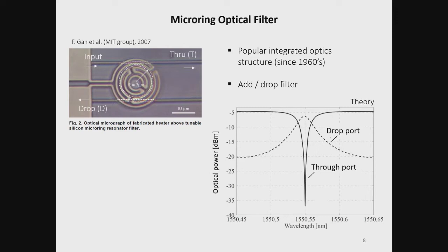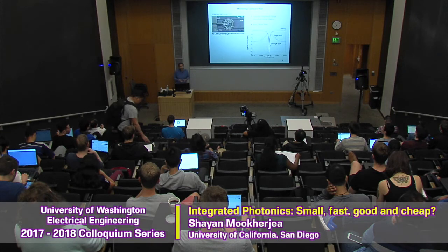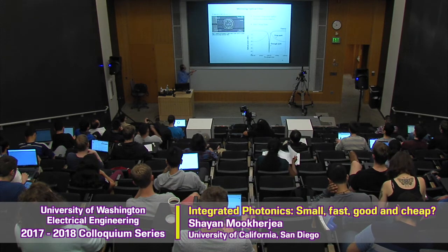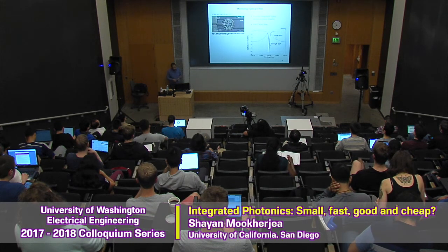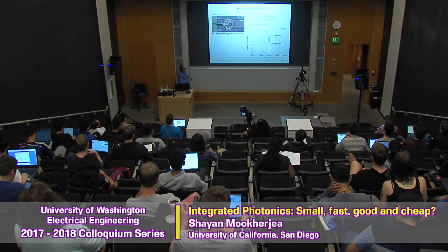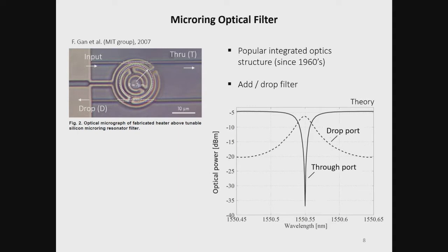In this particular example, you can't see the optical waveguide. That's sort of intentional. I'm trying to show integrated optical examples. There's a micro heater on top of it. This serpentine metallic pathway is just a small heater that tunes the resonance frequency of the ring. This is popular. The cartoon of the microring, you can see it in a Bell Labs paper by Marcatili in the 1960s. It's been known as the thing you want for sensors, for add-drop filters, and it has this single pole drop. Here's where you get at the drop port. One of the wavelengths gets picked out, and there's a notch or a critical coupling now in the through port.